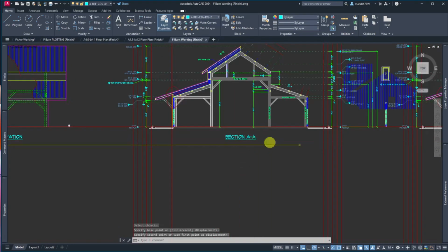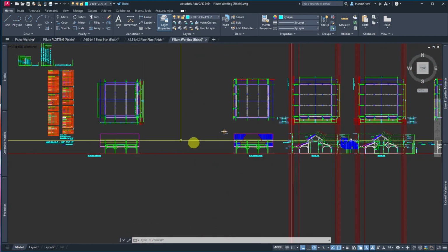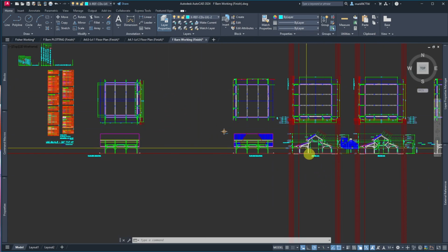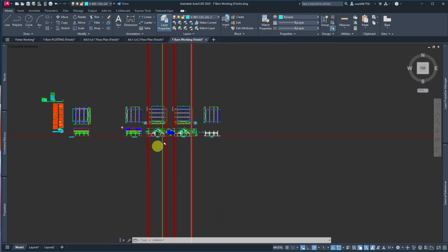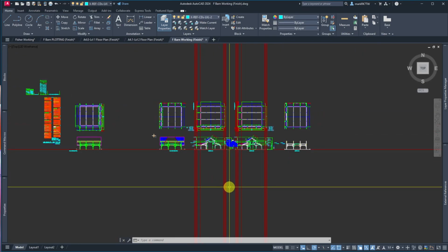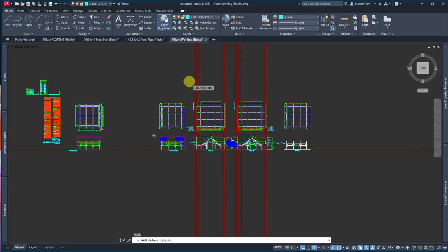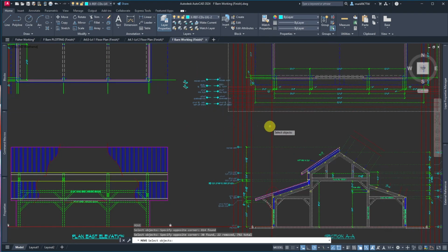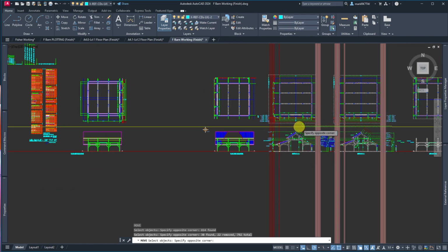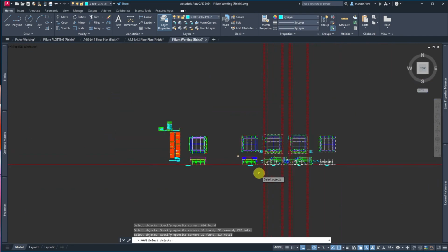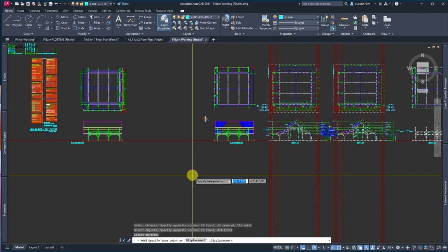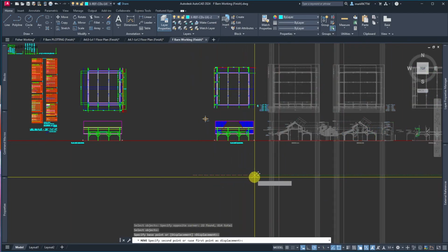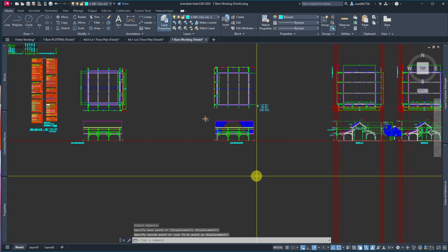So now I've got section AA, BB, CC. I'm going to need 2 elevations. So we'll have one here, and we'll have one here. So I'm going to move all sections down 1 spot to make room for this. So let's move all of this, less this, plus I'm going to go crossing to get my XREF lines. And we're going to make room for one more. So I'm just going to come and move it till I feel like roof pitch went to roof pitch. That's about 1. My polar tracking seems to be working perfectly. And now I've got space. So this is the front.